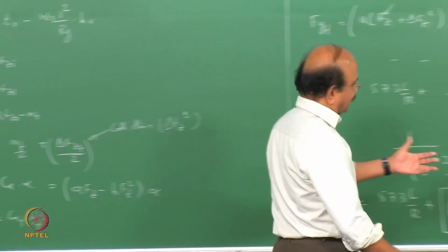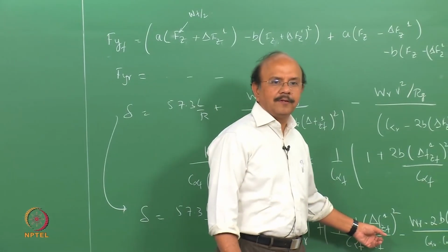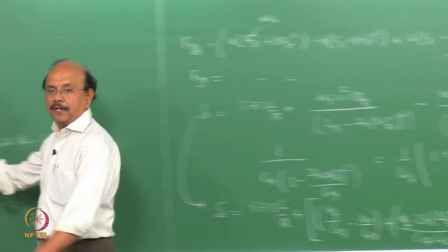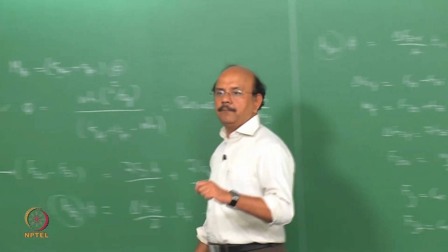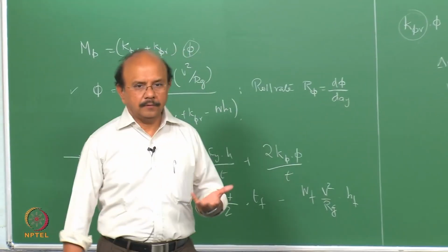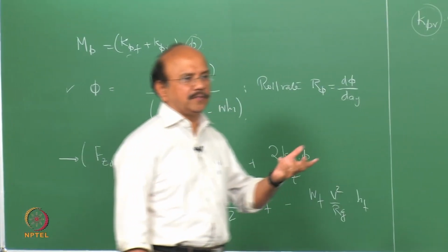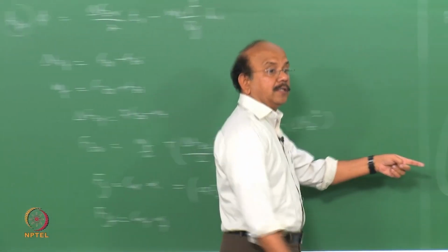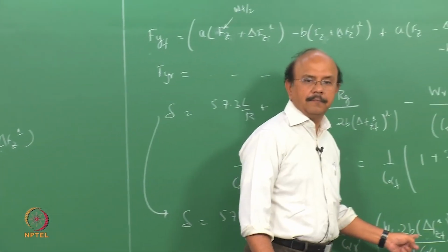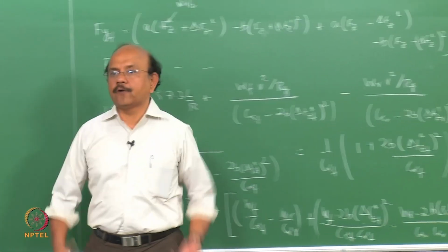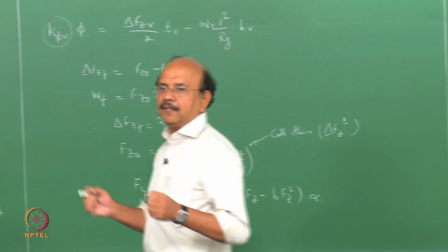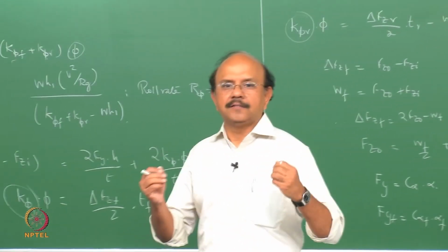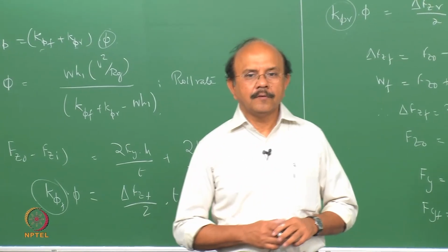So that's the first thing. The vehicle becomes understeer. So if you put a torsion bar or a stabilizing bar where the front stiffness increases, then the vehicle will become more understeer. Right? After all, we are interpreting understeer in terms of delta, the steering angle that has to be given.